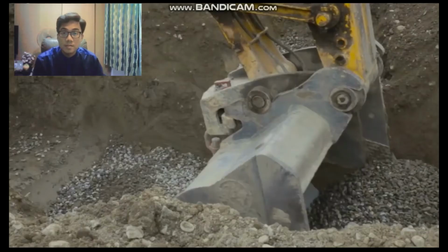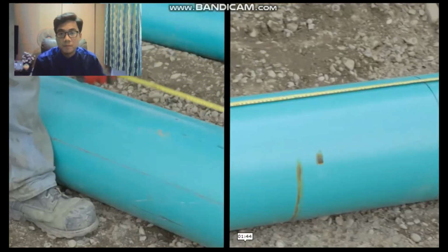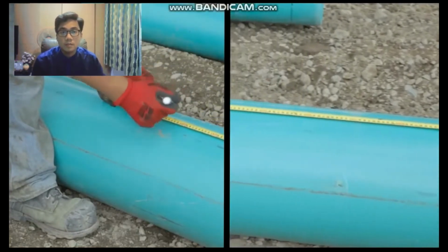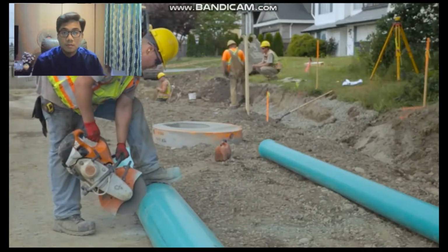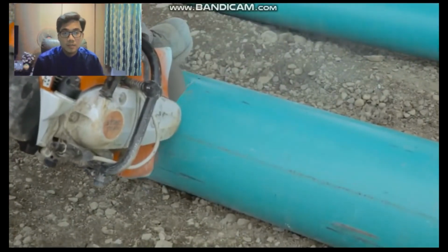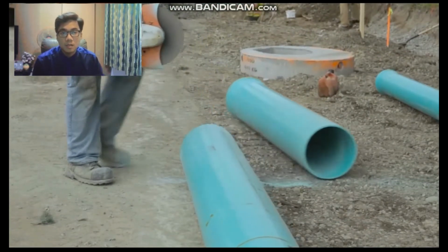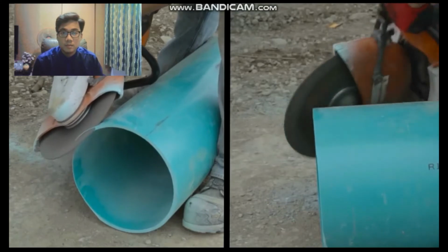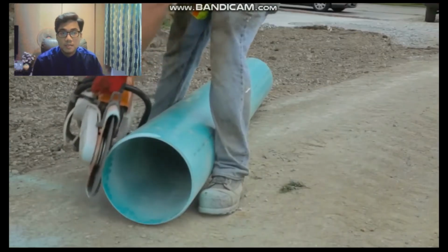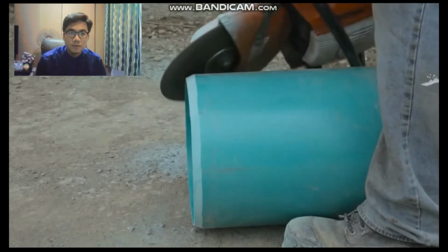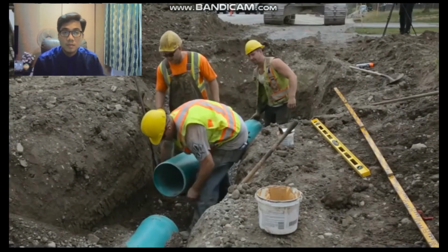Next is a little bit about manhole installation. First, we measure the distance required to cut the piping. For installation, measure the intended length, accounting for the length that will be inside the concrete base upon insertion. Once the pipe has been cut to length, chamfer and deburr the pipe that will be placed inside the manhole, and ensure the entire circumference of the connector has been equally addressed.